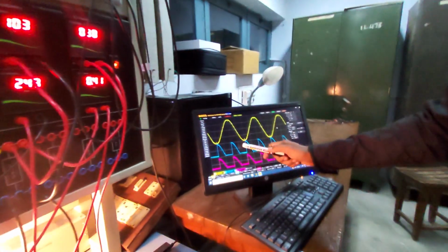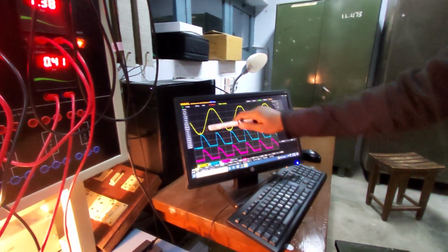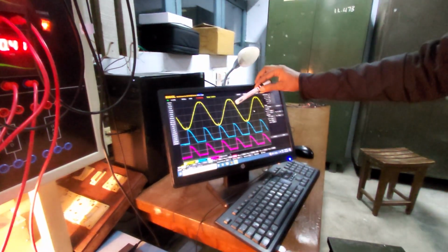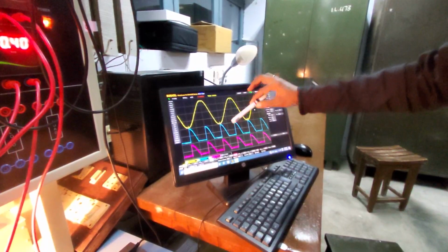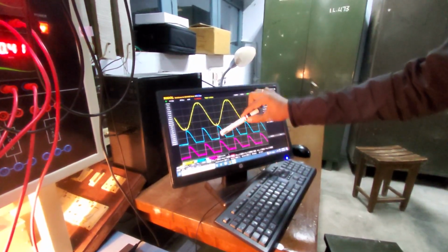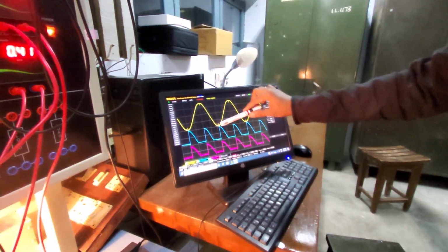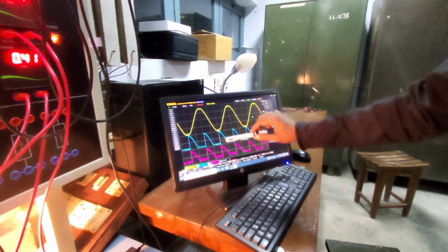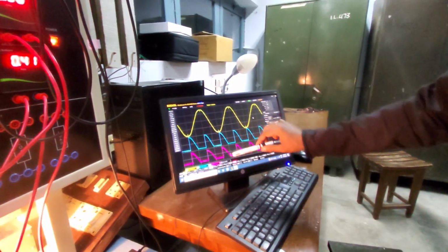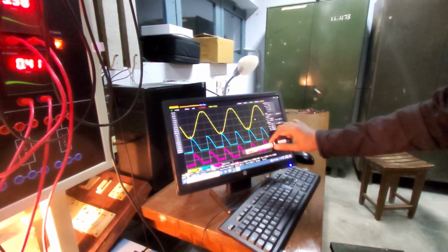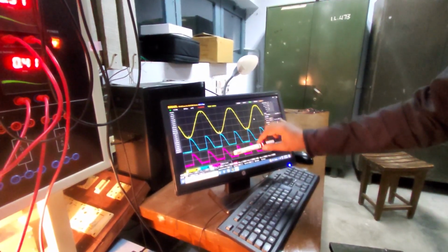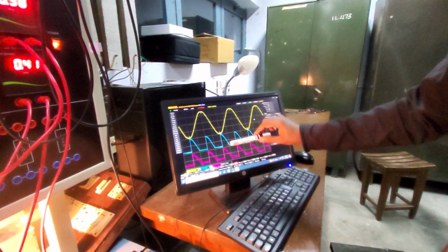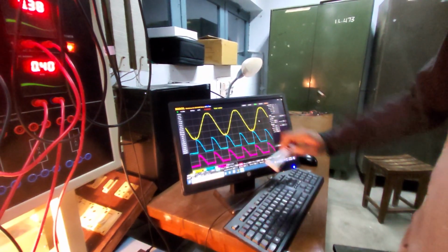Now if you see the waveforms, the yellow one is our input voltage, and now I fire at 90 degrees, so that half pulse of the input is reflected across the output voltage. As the switch is on, the current flows through that switch and the R load, so I get a waveform very similar; current and voltage are both the same.